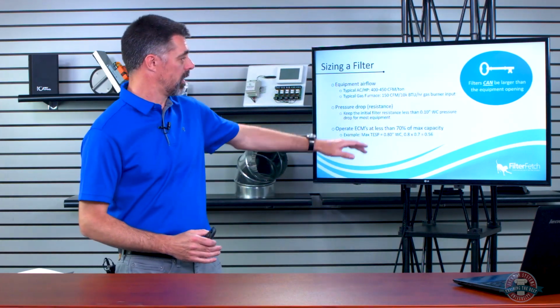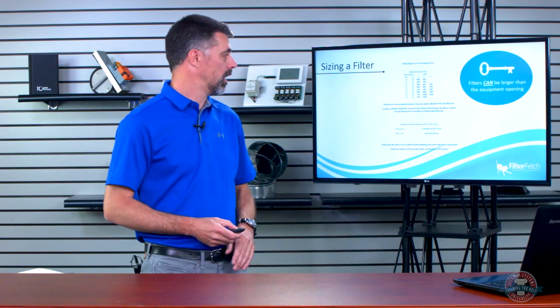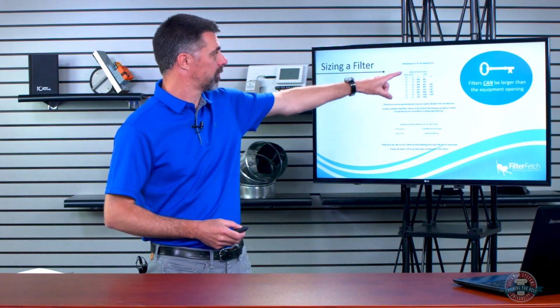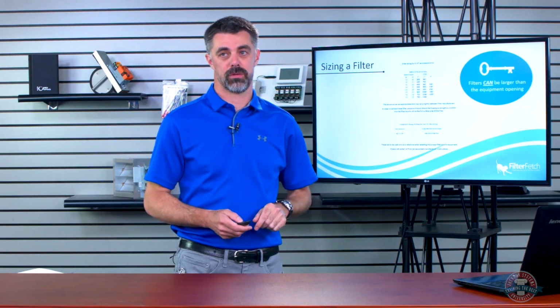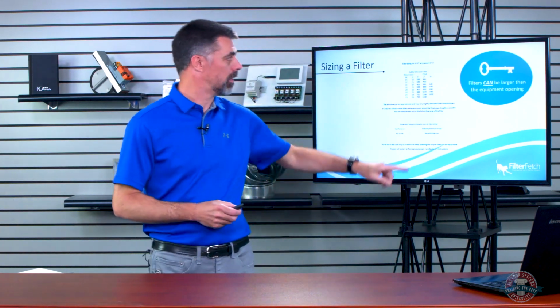In the residential and light commercial world, we need to keep this at about 0.1 inch or less of pressure drop, all right?